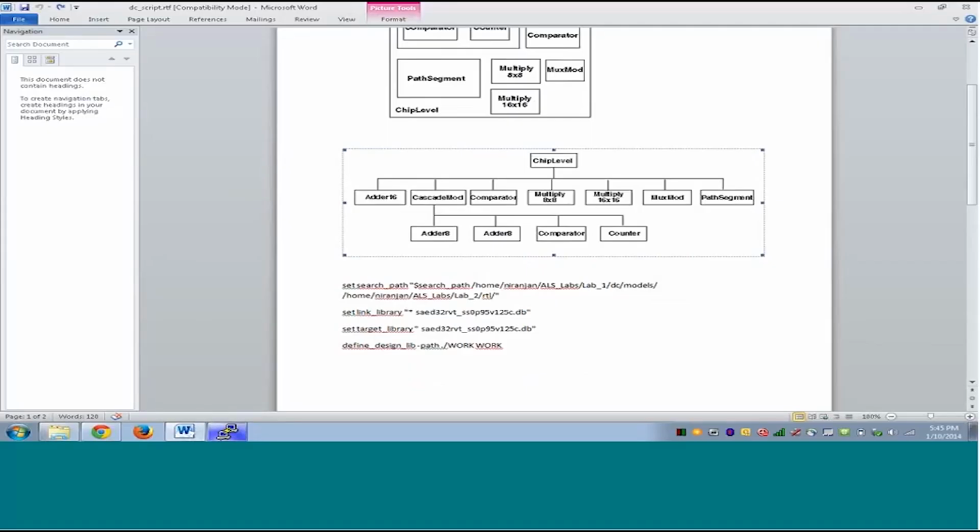You should try and make this design better in terms of timing. Area wise, don't be concerned much. You cannot do much, it's dependent on the standard cell size and the kind of design you have. The design is very simple, but you should try and make modifications to it so that you can constrain it better and make sure that there are no timing errors. It can be achieved very easily.